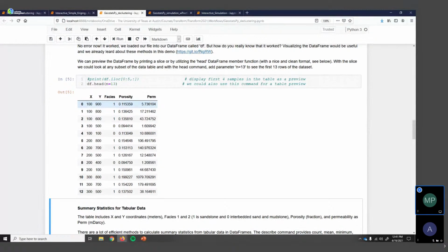The ratio of the extent in the aerial, the horizontal versus the vertical, should be related to the sampling rate. So if you have an average well spacing horizontally of about 500 meters, but your data is sampled on a meter by meter basis vertically, think of a 500 to 1 anisotropy ratio between these cell extents in the vertical versus the horizontal.